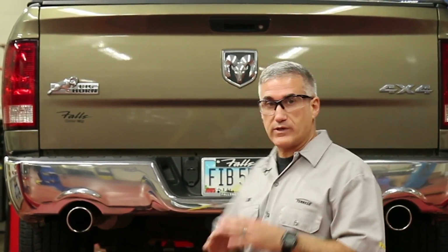Okay, so I just lifted the front of the vehicle evenly from the frame, and now I notice that the rear bumper is level, so that indicates I don't have a spring issue on the rear of the vehicle. The spring issue is with the front of the vehicle.